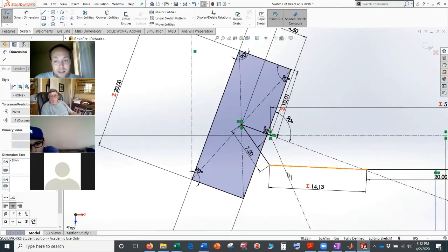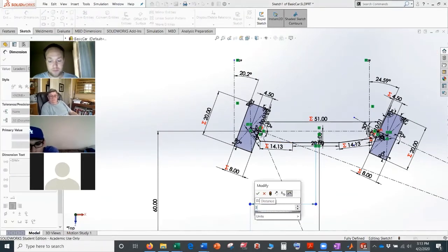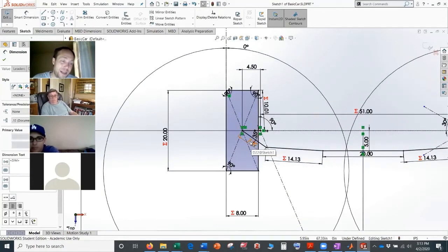Yeah, I mean, our sketches don't have that. The ones that I've used and sent to Formula as well, the steering axis is just right on the center. That makes sense, because it might be at an angle. Keep in mind this is 3D, so this axis actually moves in space. Where's the steering axis? In the plane of these arms, right? So you want to make a cut of the car at the height of these arms.